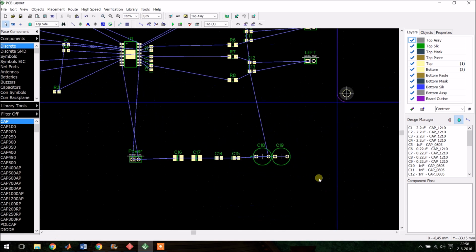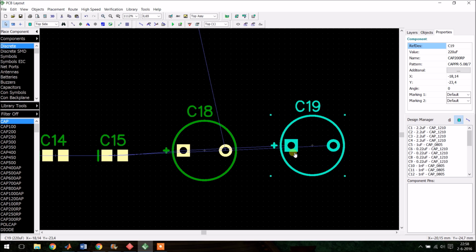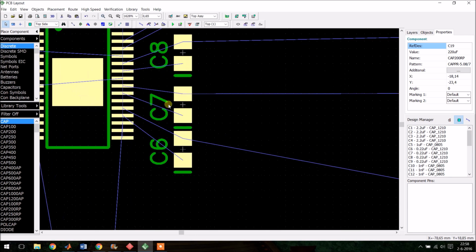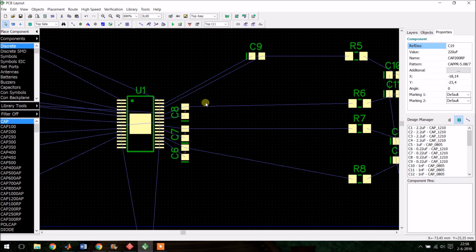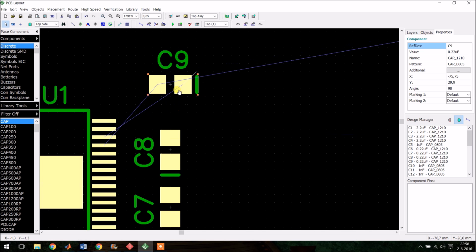If you see these capacitors here, these are polarity dependent. If you wire them up the incorrect way, they will let some smoke out and they won't work anymore. These on the output will be simple ceramic capacitors which don't have a polarity. Put down this here.